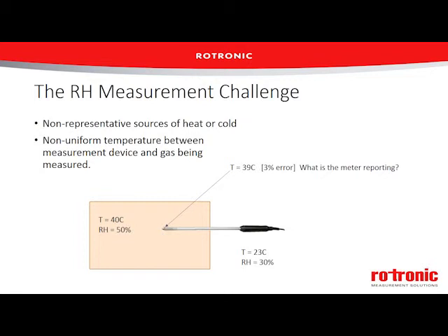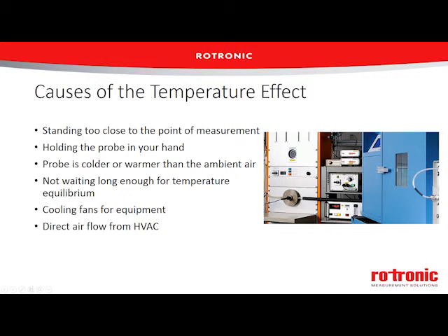There are several other causes of temperature effects in our environments. Us as users are often one of those things that can cause a temperature effect, either by holding the probe in our hand. If we're measuring a room that's at 23, our hand's going to be warmer than that typically. So we could end up heating the whole probe up depending on how big it is, which creates a microenvironment, and now we're not measuring what we want for the room. Our bodies are heat generators. If we're too close to the probe, we can be changing the temperature.